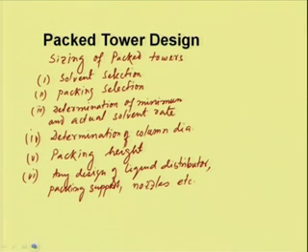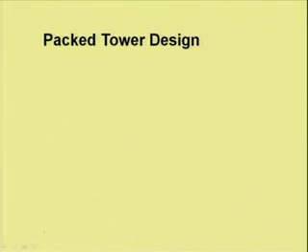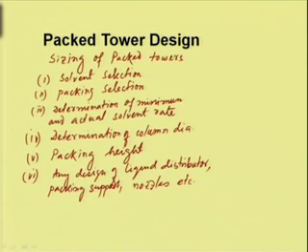In our previous few lectures, we have considered the steps: what are the criteria to select the solvent, how to select the different types of packing, and how to determine the minimum and actual solvent rate. We have seen how to determine the column diameter.